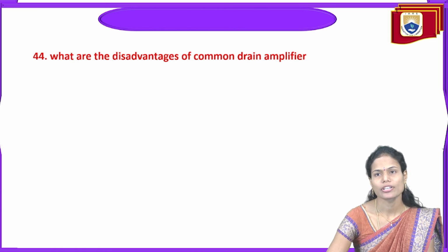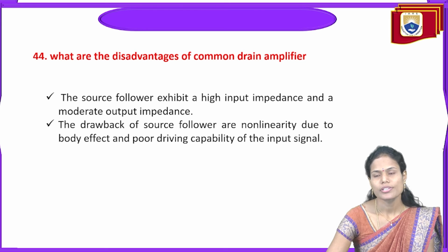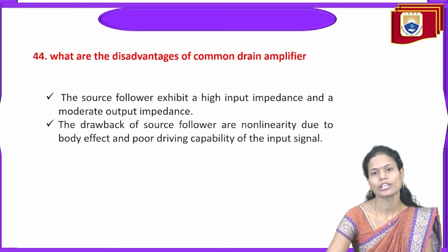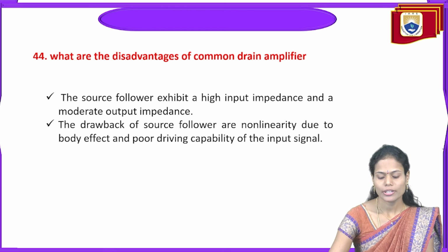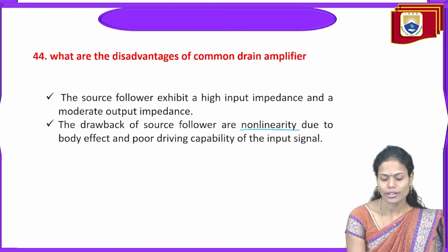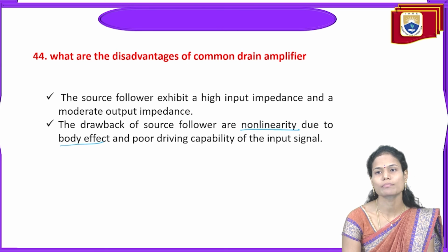What are the disadvantages of the common drain amplifier? Even though it provides a very high input impedance and a very low output impedance, it introduces non-linearity due to the body effect, as well as poor driving capability of the input signal.